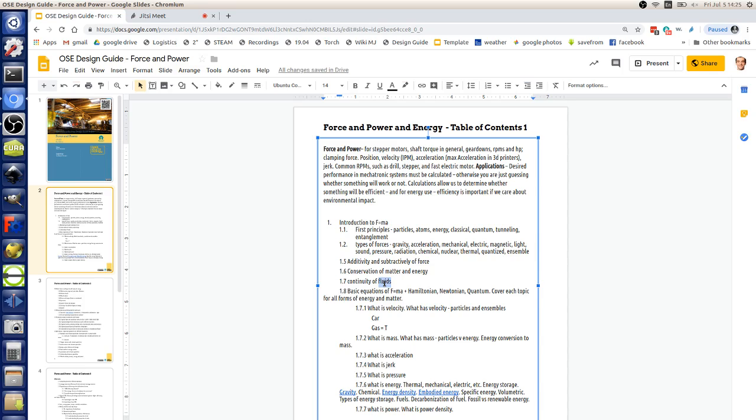In 3D printing, we also care about jerk, which is the change of acceleration in time. You can actually, in 3D printing, have that as one of the settings. So say you're accelerating, but you might be accelerating faster at one point than another. I haven't really run into that until 3D printing. I've never actually heard of it in school, but in 3D printing, it is actually quite relevant.